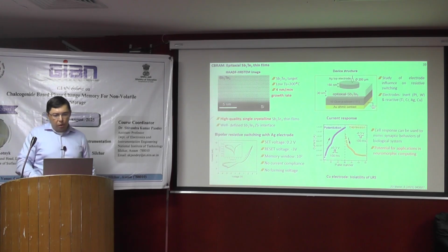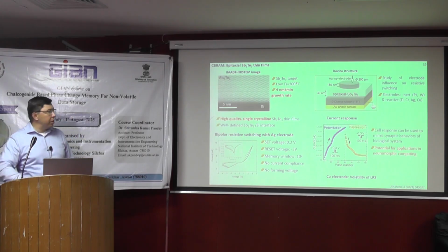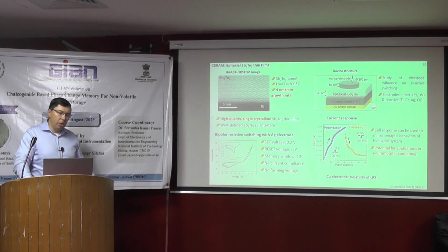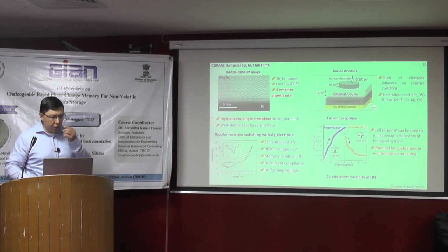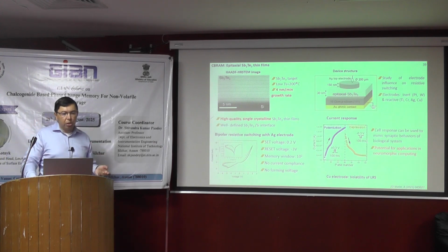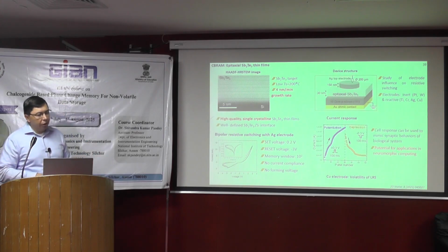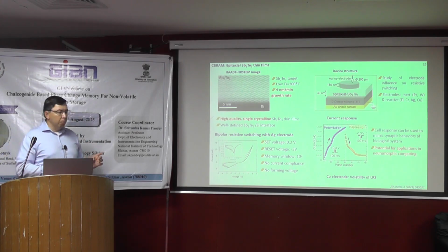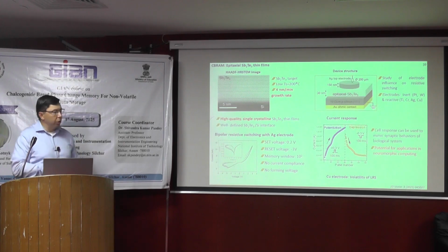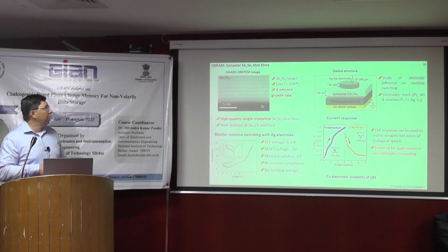If you think about the problem of resistance drift, instead of using amorphous to crystalline phase change, we can use epitaxial thin films. They are fully crystalline. And here we also made some tests using epitaxial thin films. We constructed CBRAM consisting of a silver top electrode, epitaxial thin film, and p-silicon.